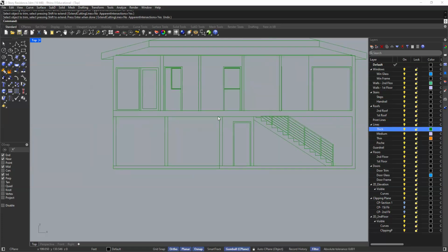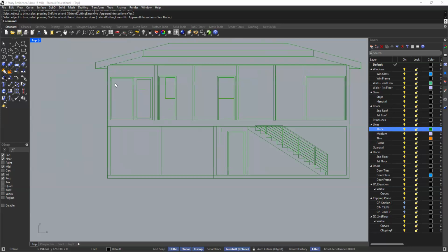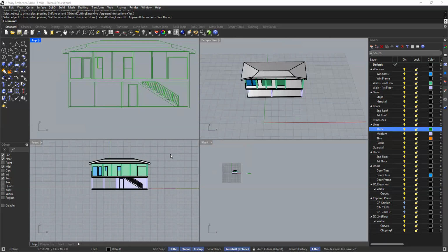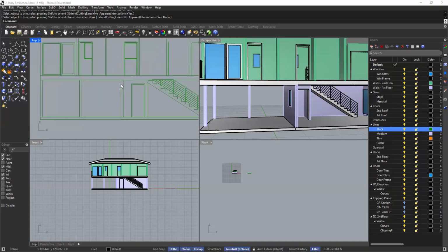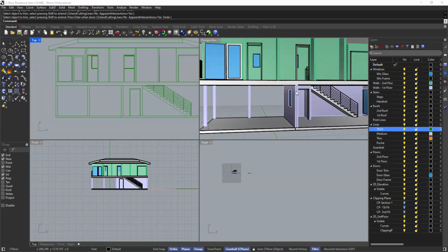Now this is where it gets a little bit confusing, because if we go back, and this is really important, make sure that you're always going back and forth between your drawings, especially if you're confused about something. So technically, this wall is that wall, and this wall is being cut through. So this wall will have a poche, and as will the floor. But because this is an orthographic drawing, it looks as though these two columns are also part of the drawing, but they're not. Well, they are part of the drawing, but they're farther back. We're not cutting through them, right?